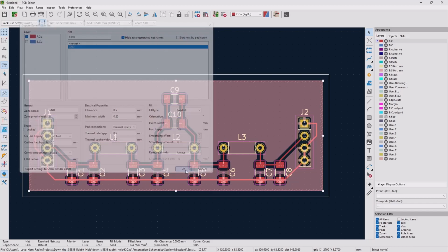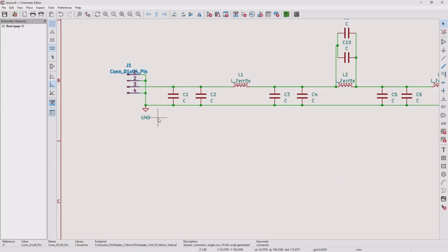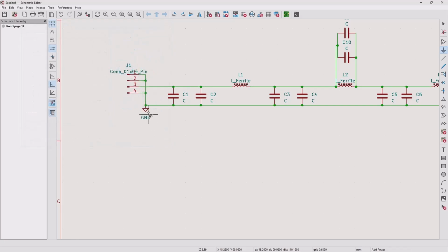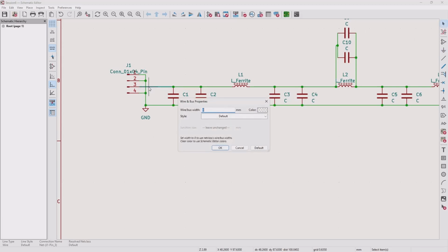I didn't have to type that in because it actually came over from the PC board because I added this signal. If you go over here, you'll see there's add power symbols, and anything that connects to this, it actually adds it to what it calls a ground net. We could actually go over here, double click on this, and give it a name. You can give your nets a name. So I could name this signal and then we would see a signal as another net there.